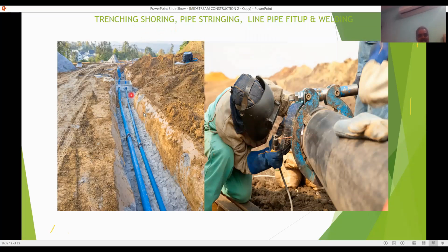Whenever you do the trench, it should be shored. The shoring should be at some angle, some 30-degree angle should be there, because you may go to 1 meter, 1.2 meters depth. For lengthy lines, it may collapse. To prevent the collapse, there should be more width and shoring excavation to be carried out. Okay. Once the shoring excavation is completed, then you fill the sand.